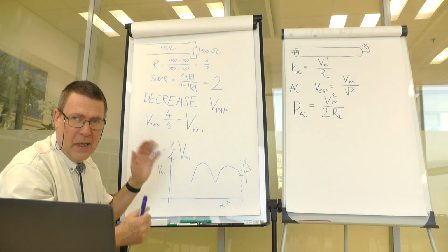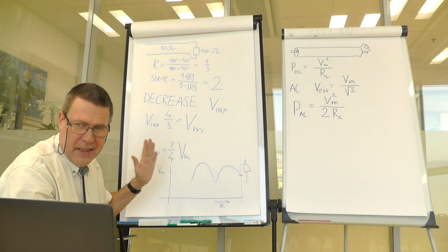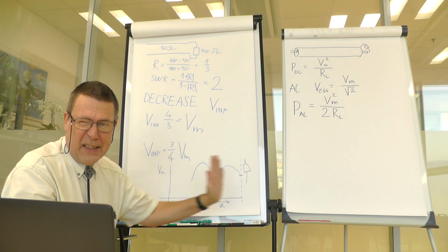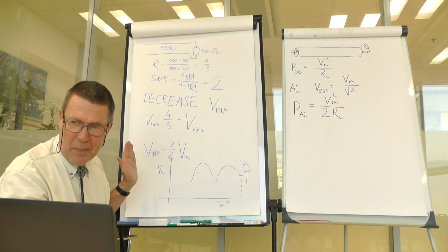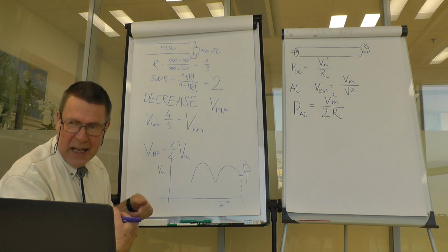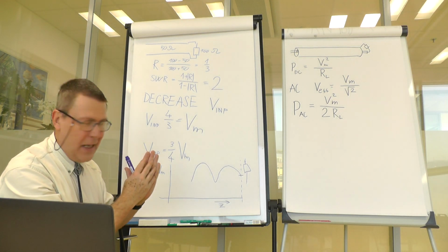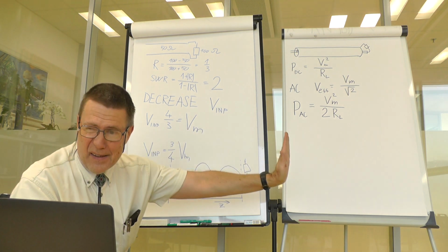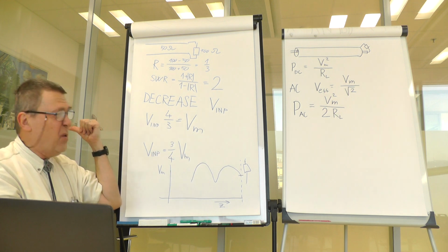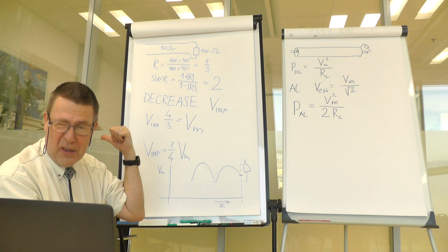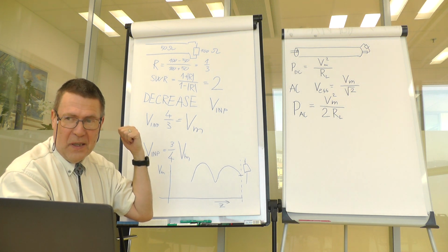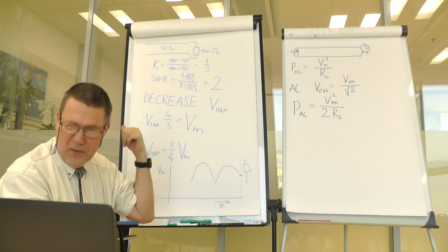So we will have to decrease the power that is submitted to the line, and at the same time not the whole power would get into the load. Some of that would be reflected back. Now we can calculate how much power would be reflected back. We have a transmission line, we have a wave carrying some power there, and we can calculate how much power would be reflected back, because the power carried by the wave is proportional to the square of the voltage.